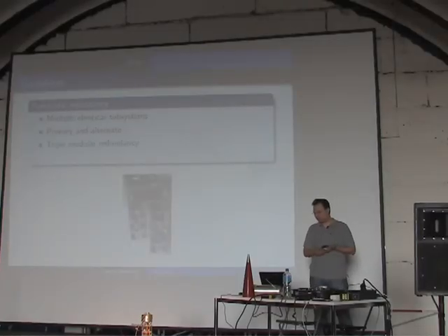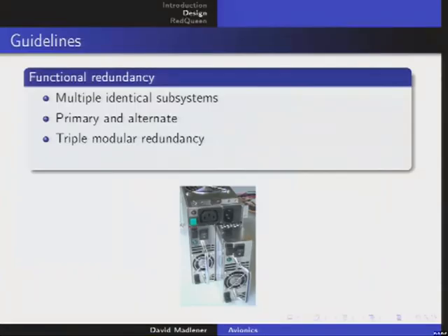And what is often used is triple modular redundancy, or even more, with 5 systems or so, where 3 systems run synchronously, performing the same actions with the same inputs, and then there is a voting logic behind them, and the majority wins. So if one system fails to compute correctly, the other 2 can overvote it, and there would be no harm done. And of course, you can increase the number of systems that are competing. There's only one drawback: when the voting logic fails, everything fails too.